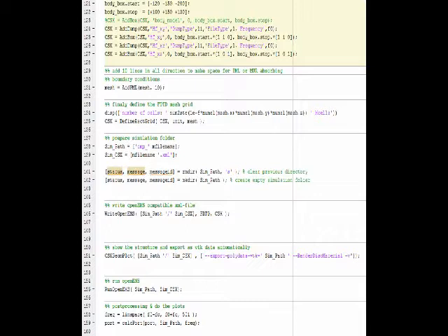the CSX structure. To prepare the simulation folder, we set up the directory as simpath and take this as input for the file name with the extension .xml, and override the sim CSX. To clear the previous directory, it is the command on line 141. The other one is for creating an empty simulation folder. After that, we write OpenEMS, activating the write OpenEMS function, taking the directory so that we can save the FDTD structure and CSX structure in that directory.